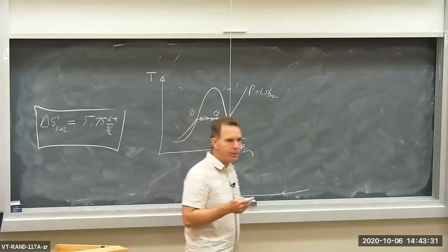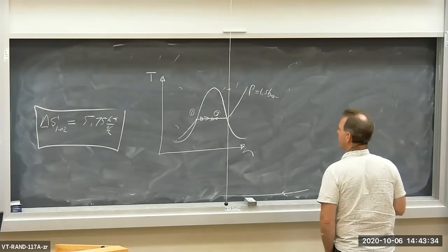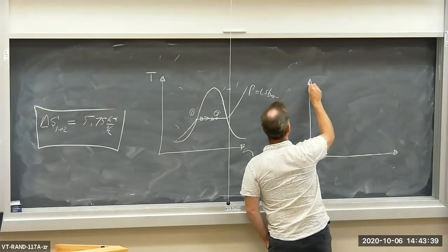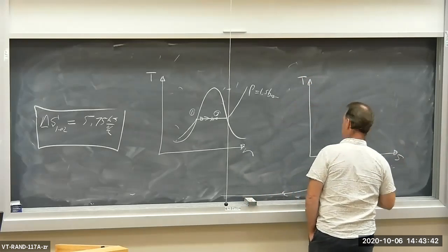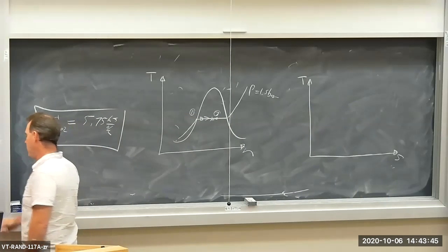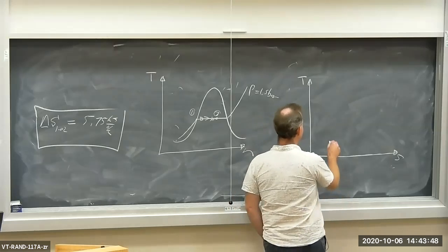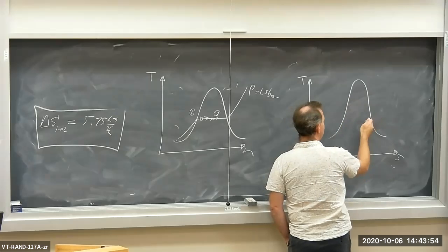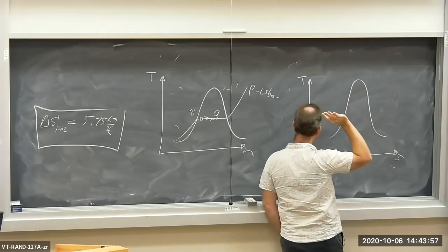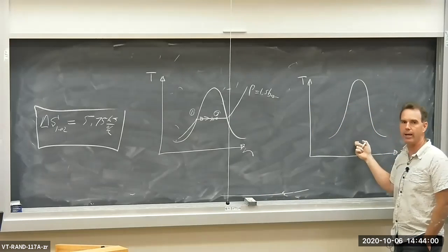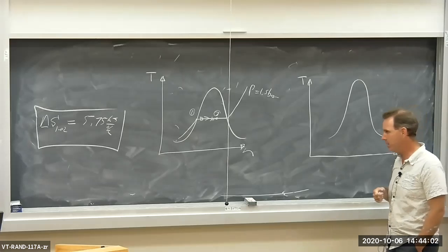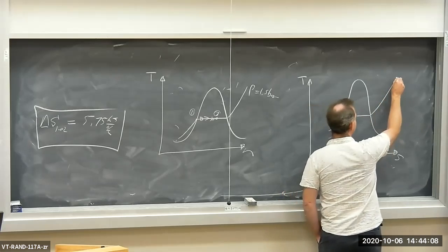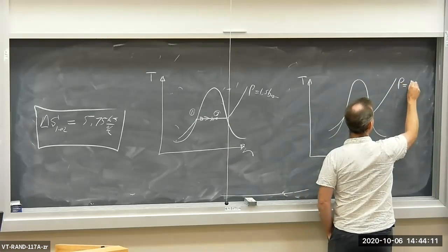Now, you could also draw the TS, specific entropy diagram, and it would look qualitatively the same. S, specific entropy, is a property like specific volume. The saturation dome looks the same for specific entropy. You have a saturated liquid over here, a saturated vapor, the critical point. Everything still applies for the TS diagram as for the TV diagram, okay? And the isobars here, again, are upward sloping outside of the dome. So P equals 1.5 bar.